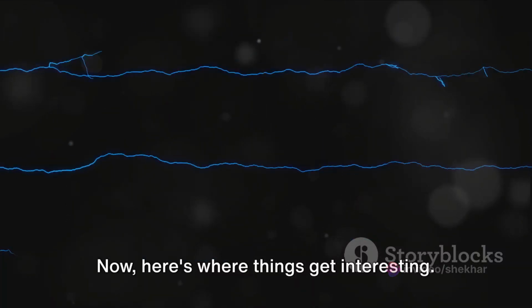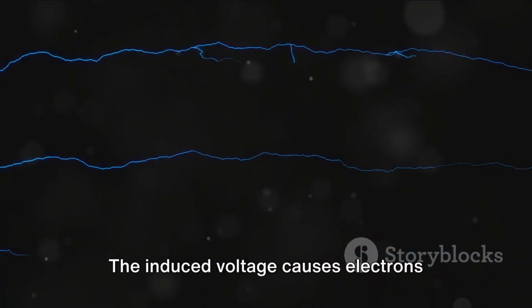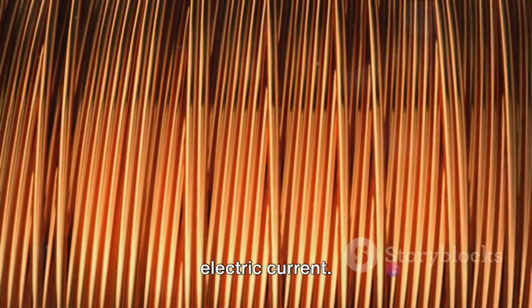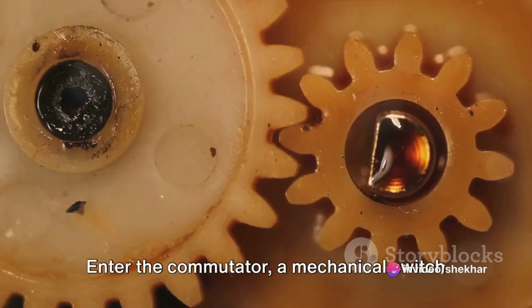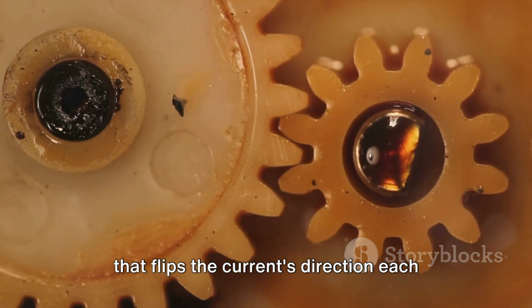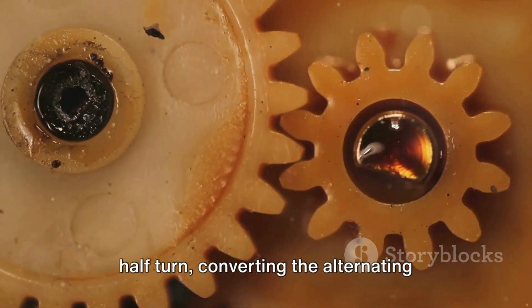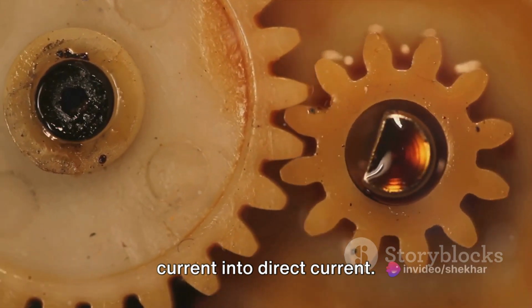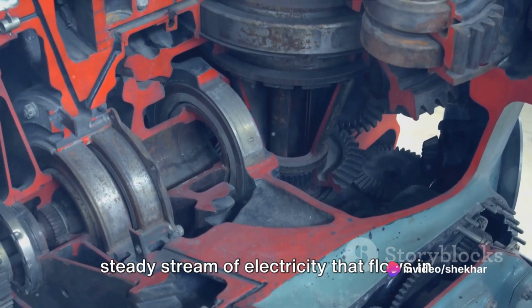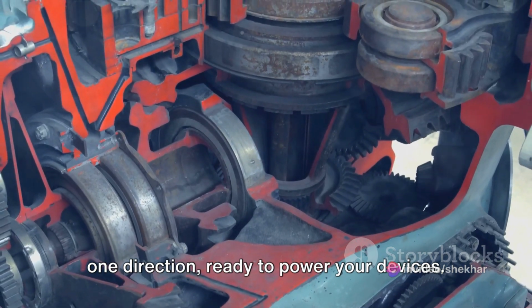Now here's where things get interesting. The induced voltage causes electrons within the armature to move, creating an electric current. But we're not done yet. This current is alternating, and we need it to be direct. Enter the commutator, a mechanical switch that flips the current's direction each half turn, converting the alternating current into direct current.